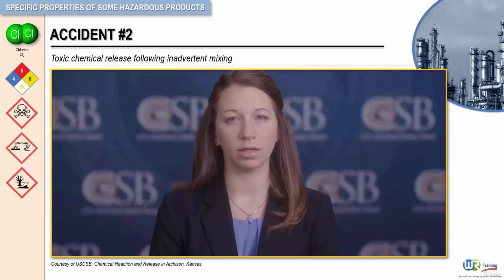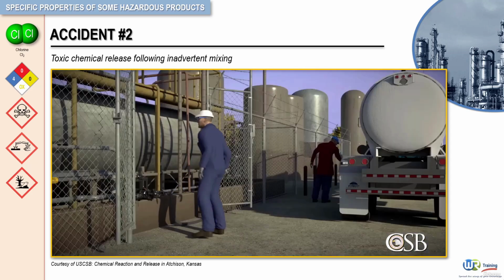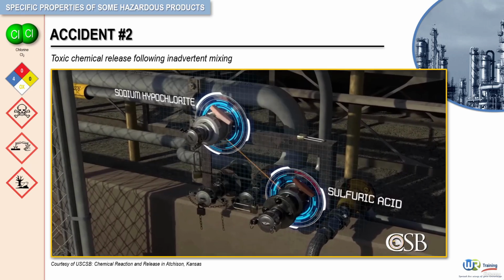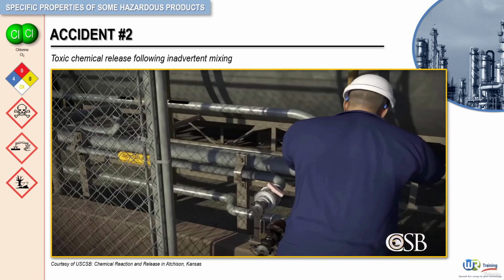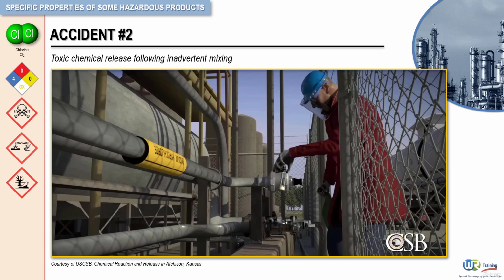A key lesson from our case study is for facilities to evaluate chemical unloading equipment and processes, and implement safeguards to reduce the likelihood of an incident. This should be done while taking into account human factors issues that could impact how facility operators and drivers interact with that equipment. This can include physically separating fill lines by a discernible distance, selecting hose couplings and fill line connections with unique shapes or colors for each type of chemical, and ensuring that fill lines are properly labeled.